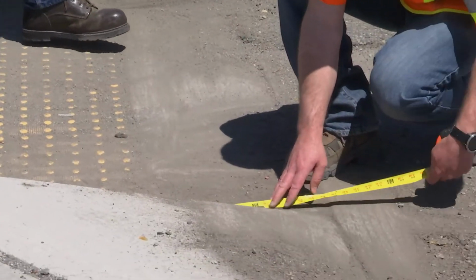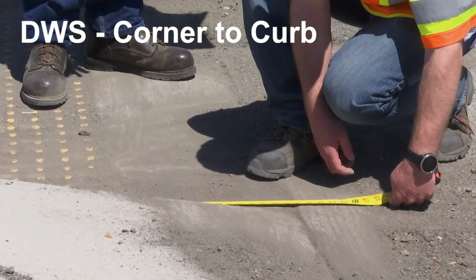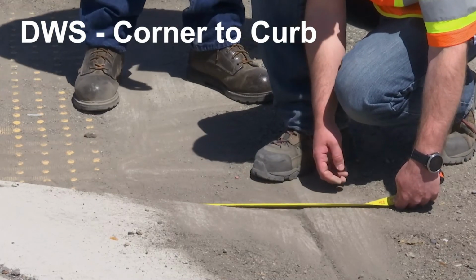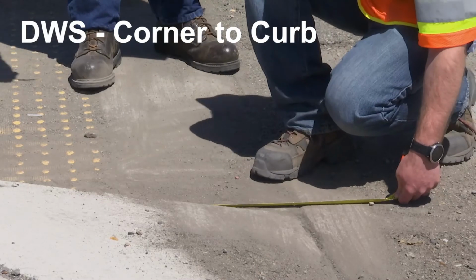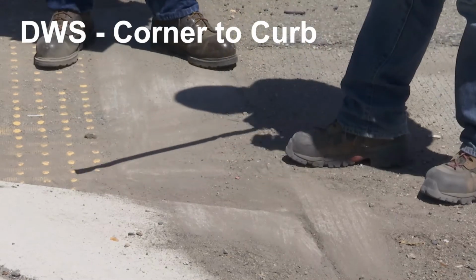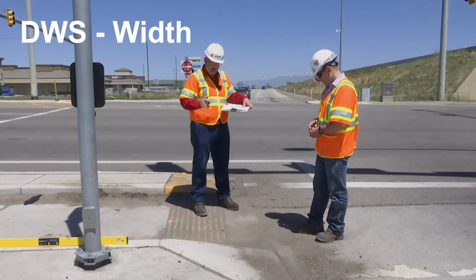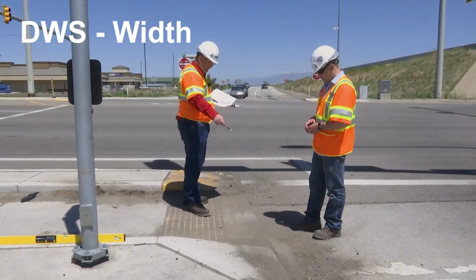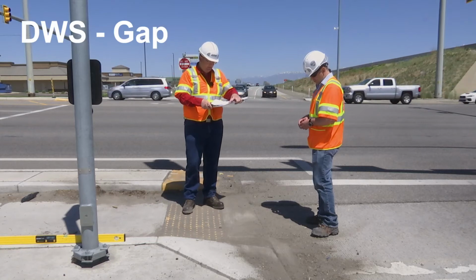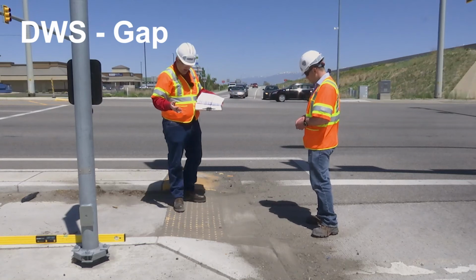Our corners. Our detectable warning surface needs to be placed at the face of the curb for all the detectable warning surfaces that are placed on a cut-through island. So our detectable warning surface we will place at the face of the curb here, it is 18 inches back from the face of the curb. So in order to be compliant, we should move the detectable warning surface up to be right on the face of the curb. And we just need to make sure detectable warning surface spans the full width of our cut-through island. In this case, it does. And lastly, we just need to make sure that there are no gaps in the detectable warning surface itself. In our case, there are no gaps.